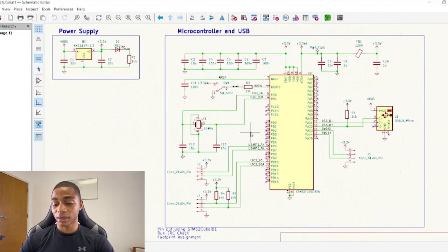Now, our last signal over here will be our BOOT0. And our BOOT0 is connected to a switch, as you can see. And the way BOOT0 works is if BOOT0 is low, then our microcontroller will boot up from our main memory, and it'll, I guess you could say, continue regularly scheduled programming. So nothing will change. It'll just boot up as scheduled, how it's supposed to, and we'll get regular operation of our microcontroller.